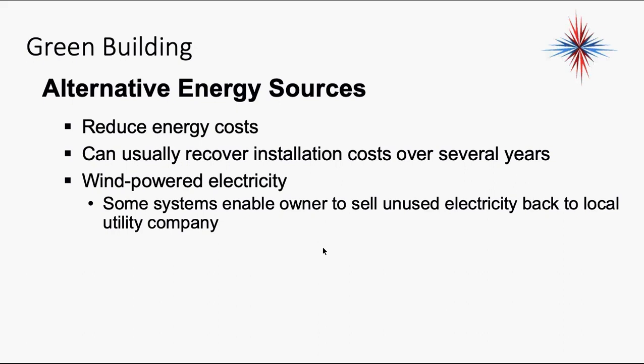So just be aware, if you pull up to a house and there are solar panels, that there are two sources of power. If things are working right and for some reason you have to shut off the main breaker to fix something, the solar energy should automatically disconnect, but always check it. It's very important, because you could get zapped by the solar cells even though you have the power shut off.